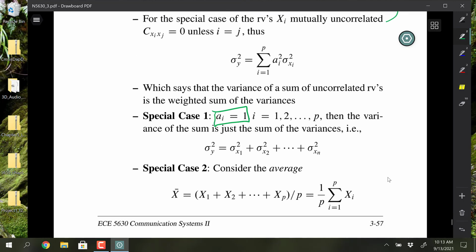Stop on this one for a second, though. A project I worked on once at RT Logic was to build a diversity combining receiver. So how did we do that? We're not talking about channel models and digital comms just yet, but this would be behind that. If you want to do a simple diversity combining receiver, you'll want to combine all of the channels, in this case it's n inputs, in such a fashion that you can minimize the variance.